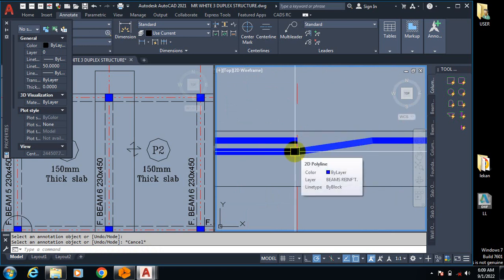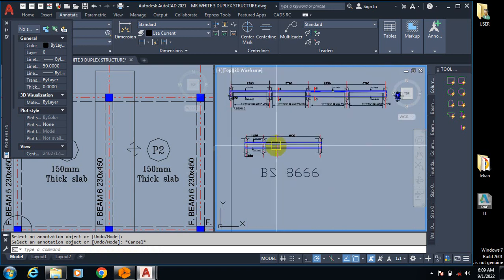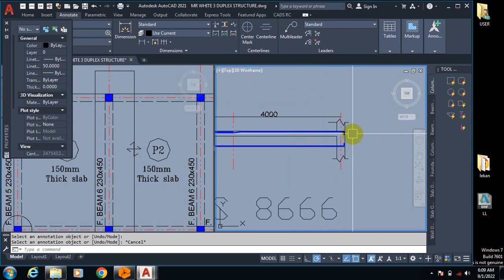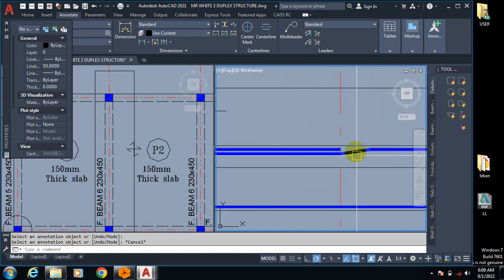It has formulas based on the kind of bending you want to achieve. All these bend shapes have their codes, in different codes. So all you need to do is lay your hands on BS8666 to be able to understand all of that. If I really want to go through all those bending codes, it's going to take a whole lot of time.